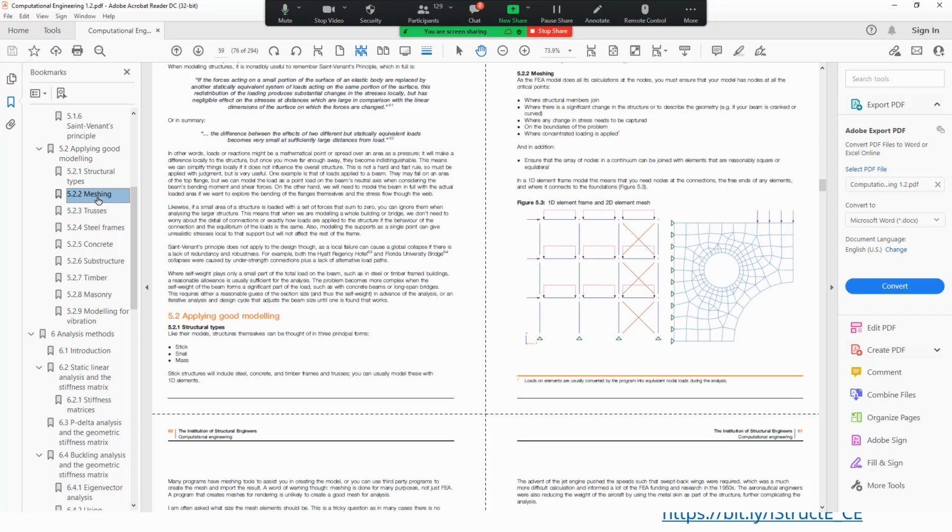If the mesh size, you have what we call a singularity at that point. As you reduce the mesh size over the column support, the moments keep going up, and an infinitely small mesh will give you an infinitely high moment. Now, the reality is you don't get that. The moments just level off within the connection size. So basically, there's no point even meshing within the connection itself, so use restraints, or stop the meshing once it gets to that point. So there are things to watch out for there.